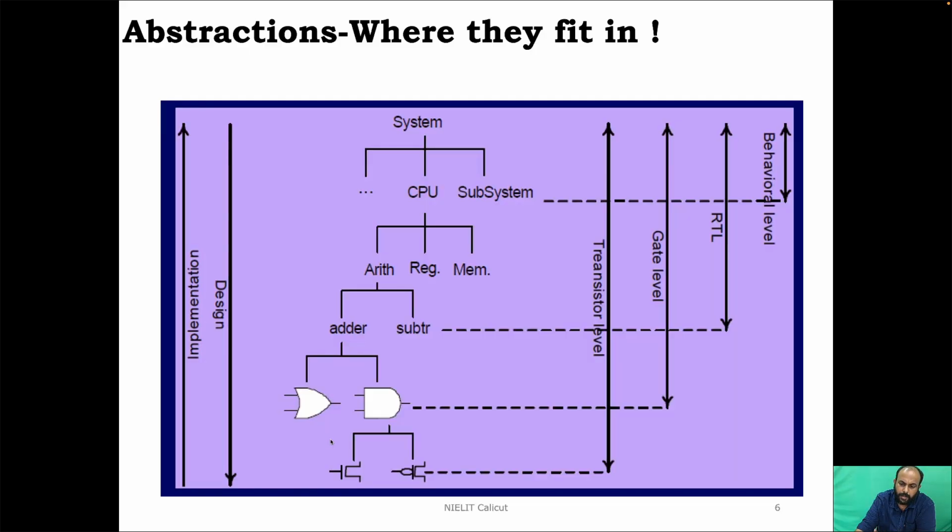So whenever you are working in a product company kind of thing, most of their products will be reaching maturity. So in that case, they will be having structural kind of descriptions, which is the most foolproof way of taking it to synthesis. The other styles include the RTL way, or say data flow modeling, wherein we are specifically telling how data flows between different components. At the top level, that is at the system level, and often when the algorithm is complex, say a DSP algorithm, those kinds of things, when there is a lot of computational complexity involved and it's more algorithmic in nature, we go for behavioral modeling.